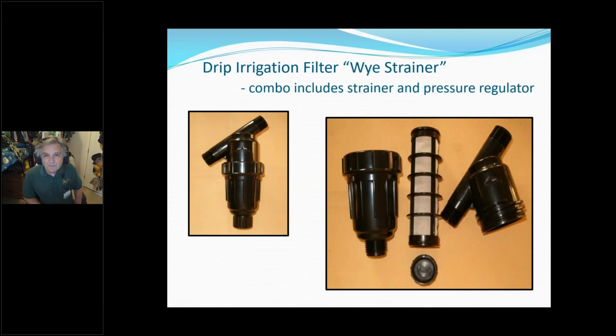And then the various types of filters or strainers. They also have straight inline filters that are very inexpensive that you could apply anywhere in line. And these take out all of the debris, all of the sand. You will not get clogs using a strainer type filter or any other type of inline filter.